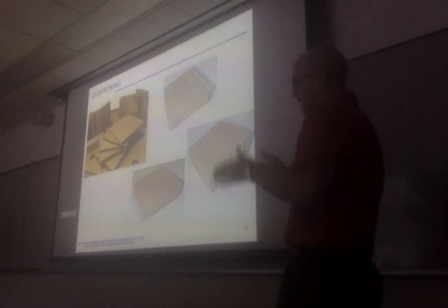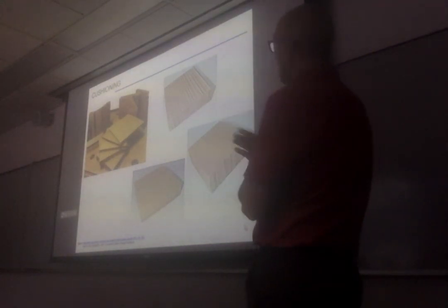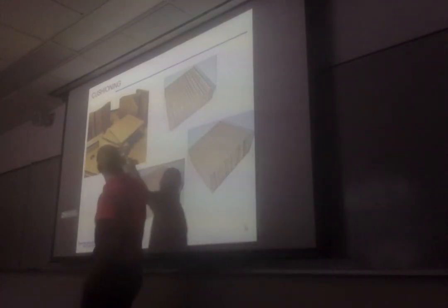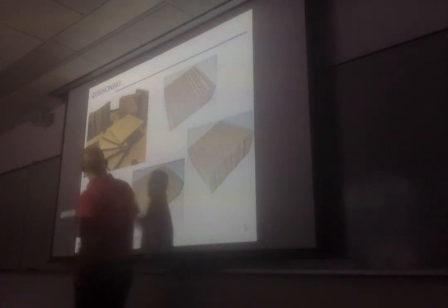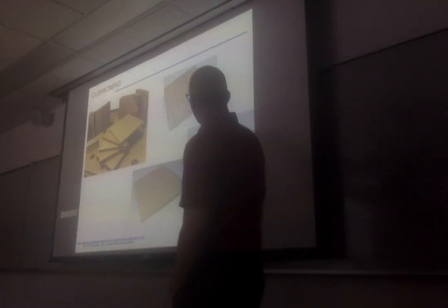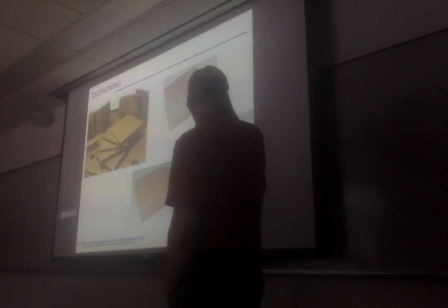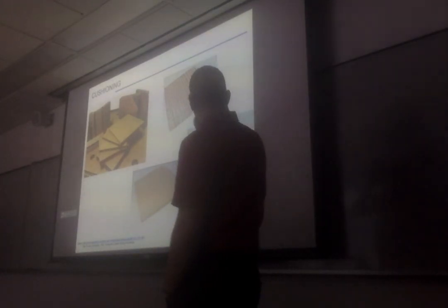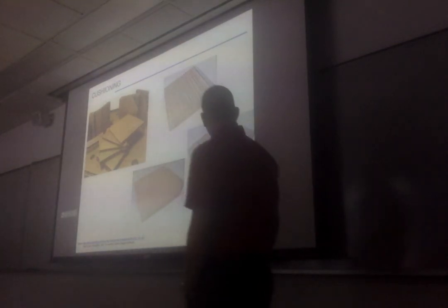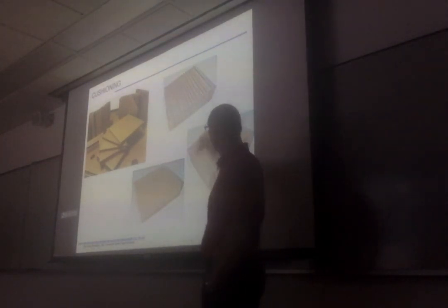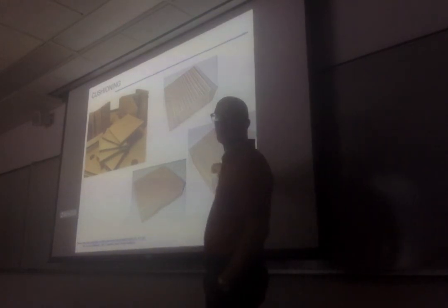If you have it in the other orientation, then you're going to have a little bit softer cushioning, let's say if the impact was in that direction. Now corrugated can be created into different types of cushion. Again, depending on the orientation, you're going to create quite different stiffnesses. If you have the flute going up vertically and you put something there, that's going to be really rigid, really stiff.